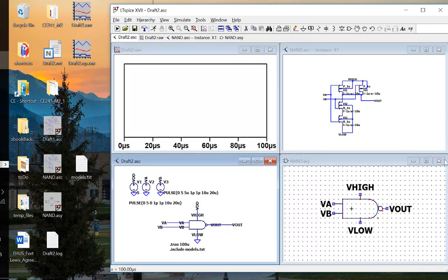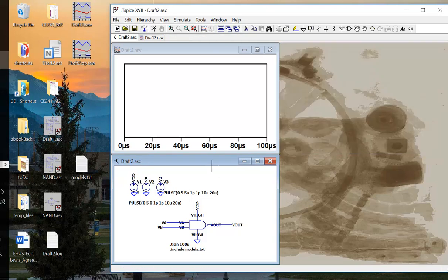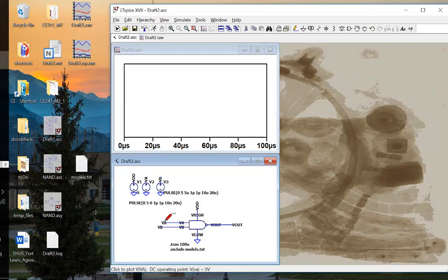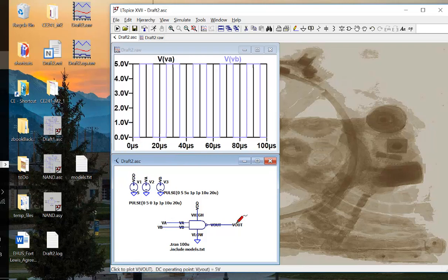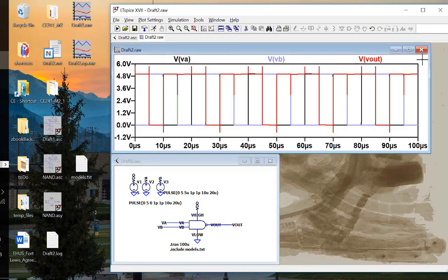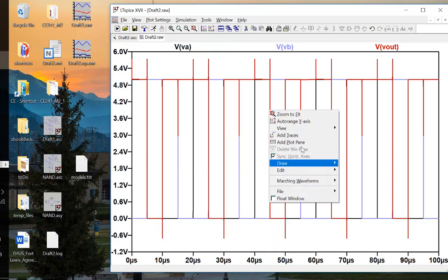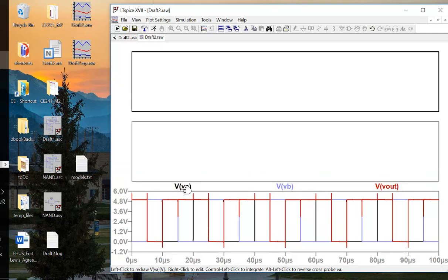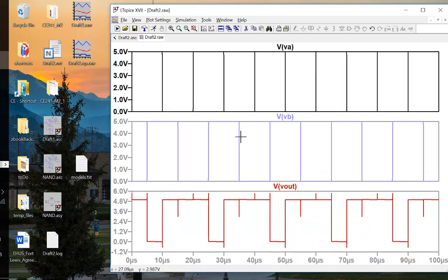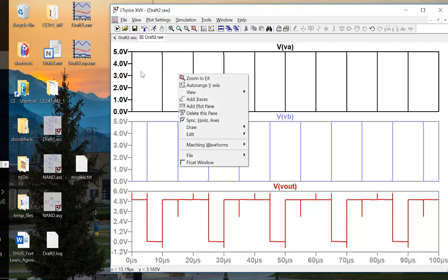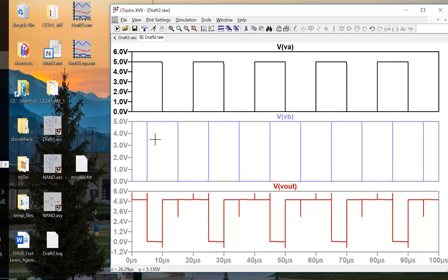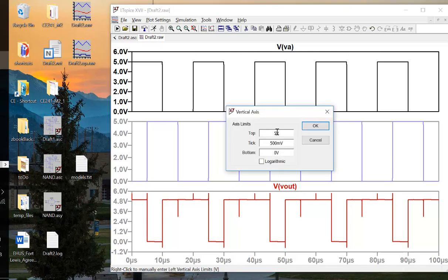Okay, now it works. Let's come back, and add signal, we can probe it. Probably that'll be easier. Let's probe VA, probe VB, and VOut, and now let's see if it's NAND gate logic. Right? I can right-click and add panel pins, VA, VB, and let's change the y-axis by right-clicking it and make it 6 volts, so you can see the 1s and 0s. Same to these.